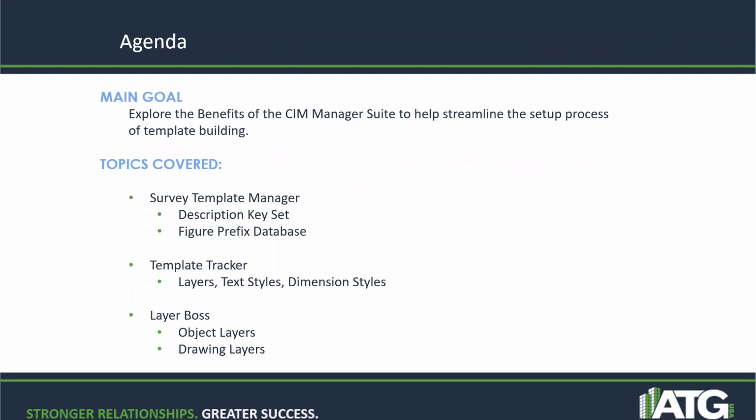And just one thing before we move on, when we're talking about the Survey Template Manager tool or the Layer Boss tool, the key here is that we're not going to be doing the bulk of that work inside Civil 3D. We're going to be using Excel or another spreadsheet editor to modify these CSV files in a way that's easy and intuitive that Civil 3D just doesn't really give us access to.